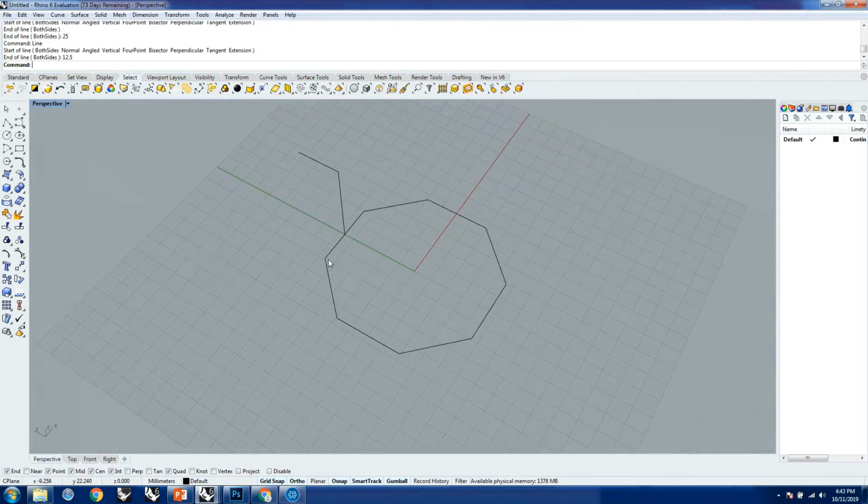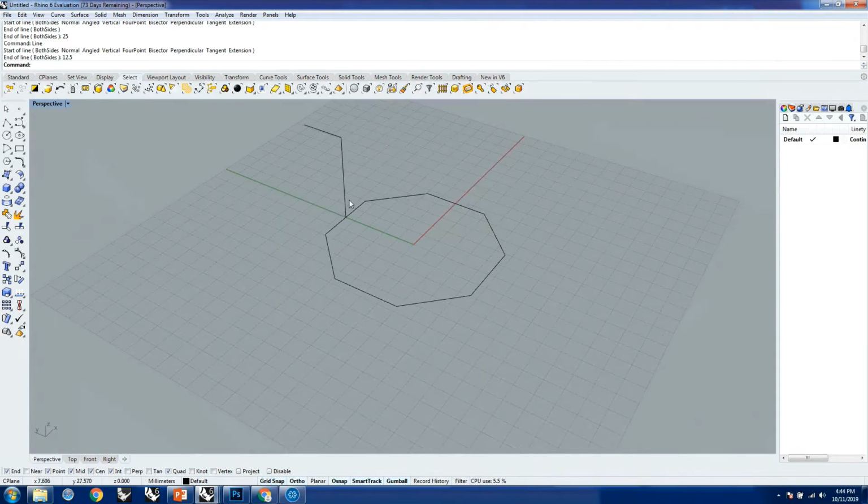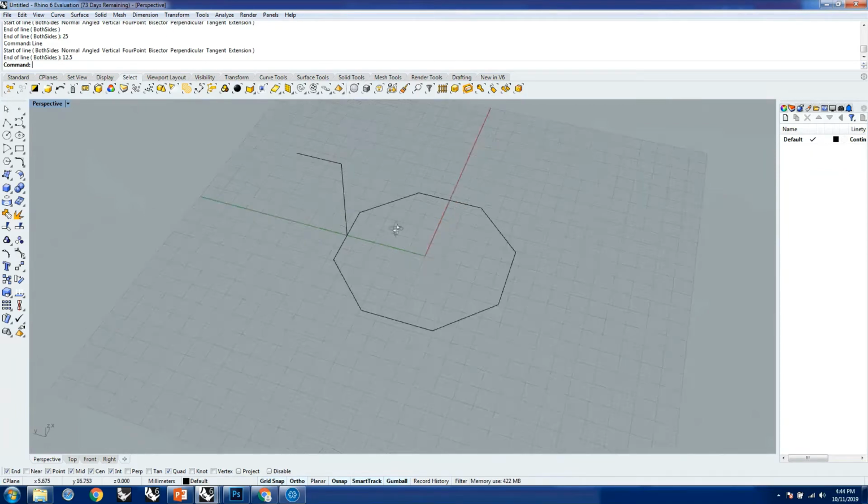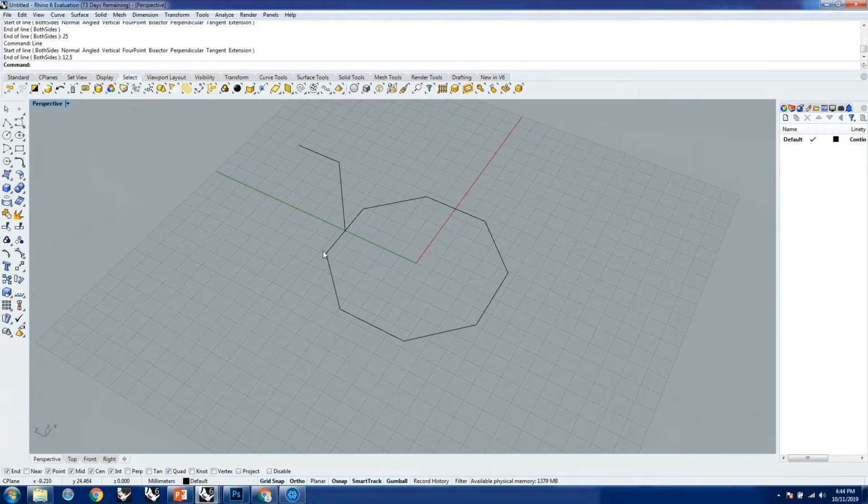Okay, so I have this point now in space, and now I can understand where I need to plot it to just use it to make a curve. So I'm going to take this one point, the second point, and the third point to make the curve, and I'm going to use interpolate curve or interp curve.